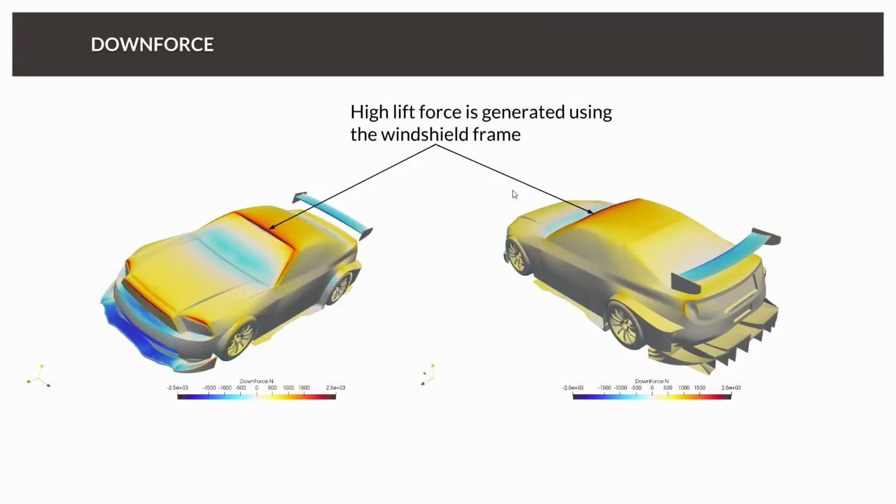You can calculate this by multiplying, for every point of the car, the pressure with the normals in x and z direction. Gray in this case means that the part is not contributing to forces in x direction at all. Red means it's creating drag, and blue means it's creating downforce.